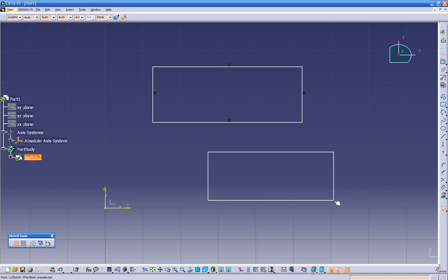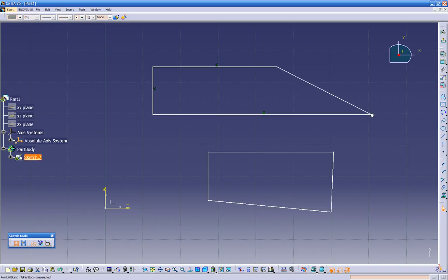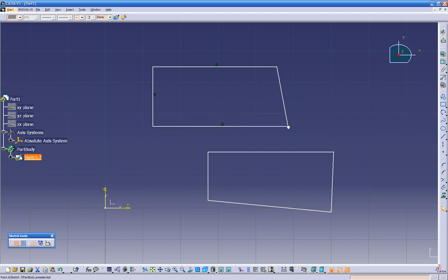We don't have the horizontal and vertical anymore. So if we click on this point, we can distort it right away. It doesn't stay because it doesn't know it's a horizontal line. This right here, it knows it's a horizontal. So if I grab this point and try to move it, it's not going to do anything to it. But if we delete the V, watch what happens. See, we still can move it. So it's not a vertical line anymore.